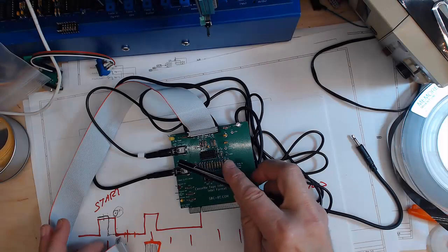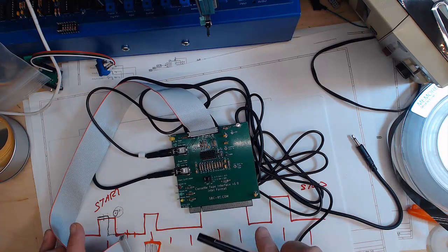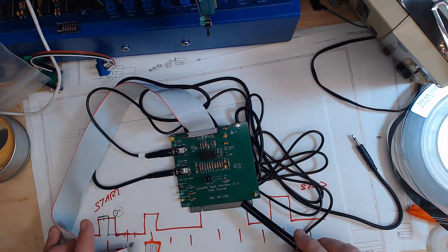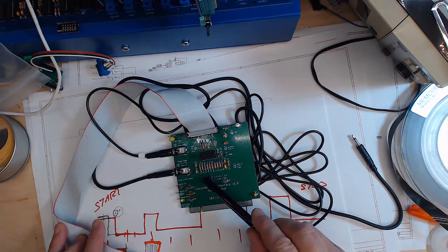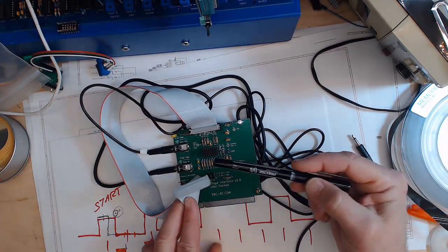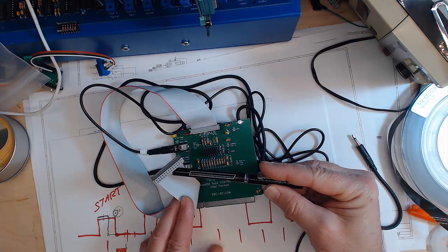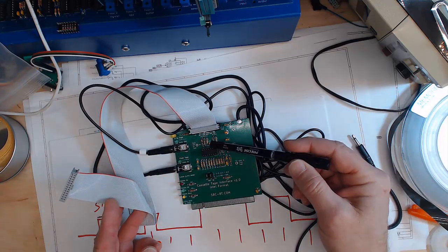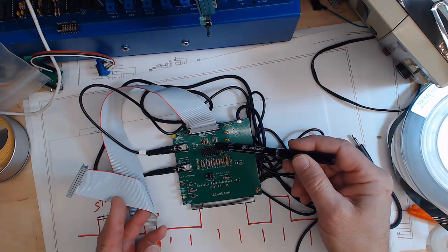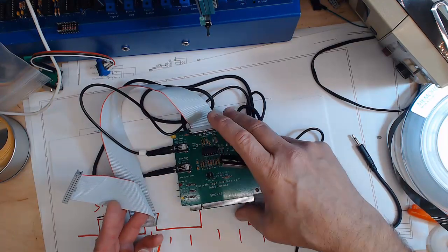This is the board. Of course, we have a line going to the tape, a line from the tape. We can use the SID and SOD on the back plane to communicate with these jumpers, but since the SID and SOD is busy with the serial port, generally we would be using this interface that goes to one of the interface ports, like on the 8155 on the CPU card. We have this quad op amp and then just the resistors and around. So it's a very simple card.